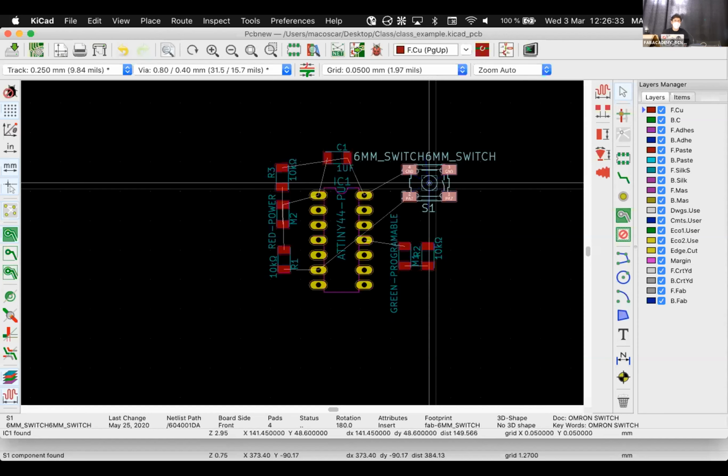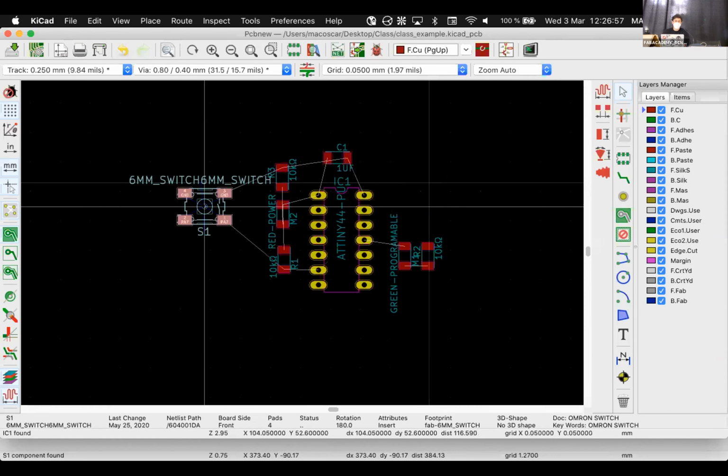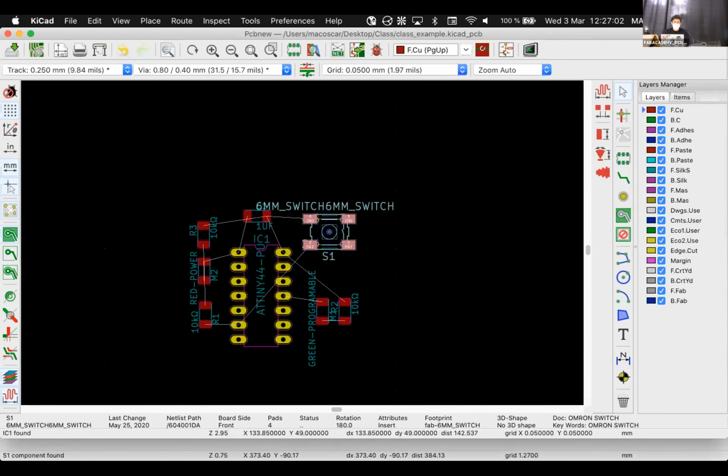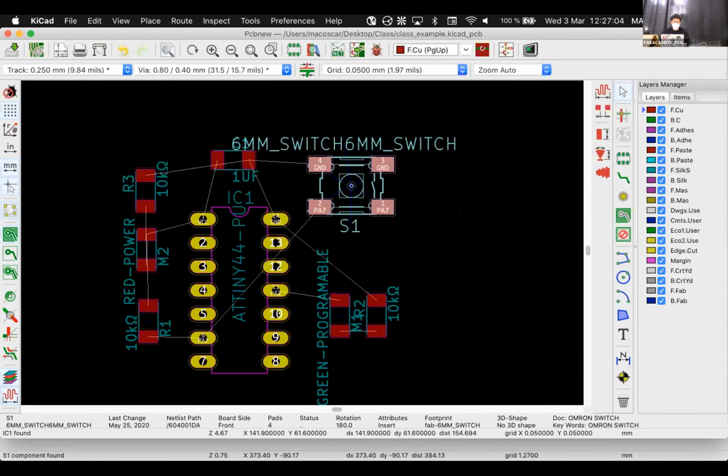It doesn't matter if it's the closest or the farthest one, you just have to connect this, okay? And you know that all grounds in the circuit have to be connected, all of them, and the circuit always has to share the same ground. I'm never gonna be tired of saying this. So if I move the component, there's maybe a closer ground somewhere else, and that changes, but it's okay. So I don't know what you think, but for me, this probably is a good place to start.